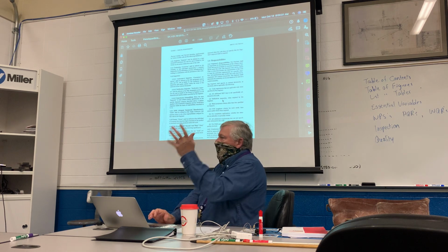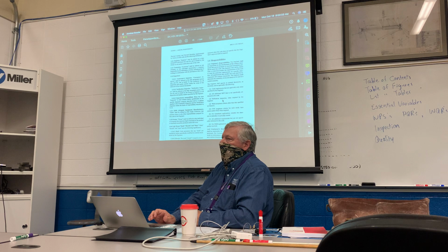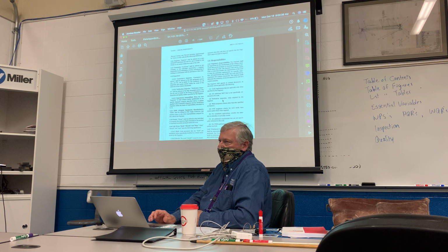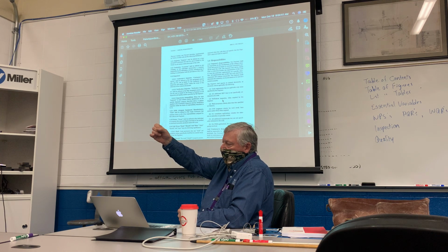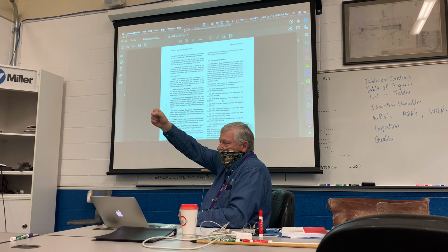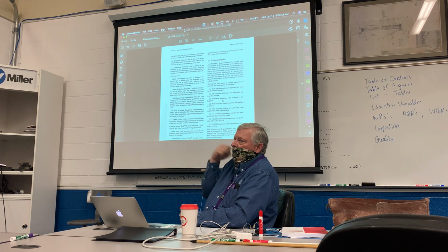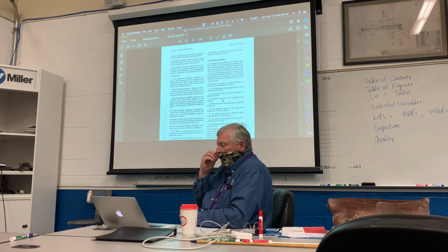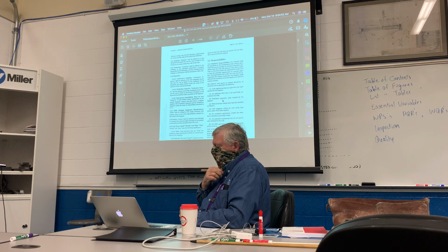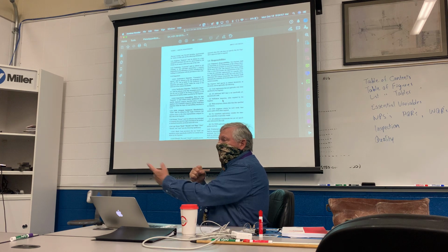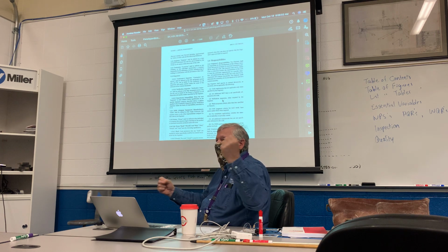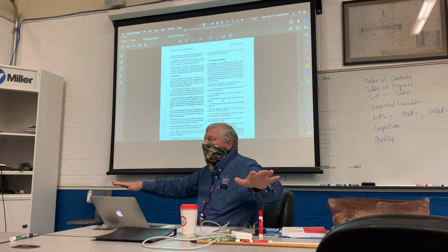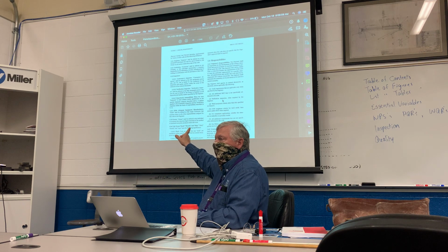Exactly. Studs. You might get called in to do a stud inspection, where you take a piece of 1 1/4 inch heavy wall pipe about 5-6 feet long, and you stick that over the stud. Basically, if you pull it to your body, you've pulled it 10 degrees, depending on how tall you are. And if it breaks, then you have to do a certain percentage in that field. As you're going through, you pick out certain ones and you bend them. And if you have no bends, then okay, you can pour the concrete now. Verification inspection that the welding was done correctly.